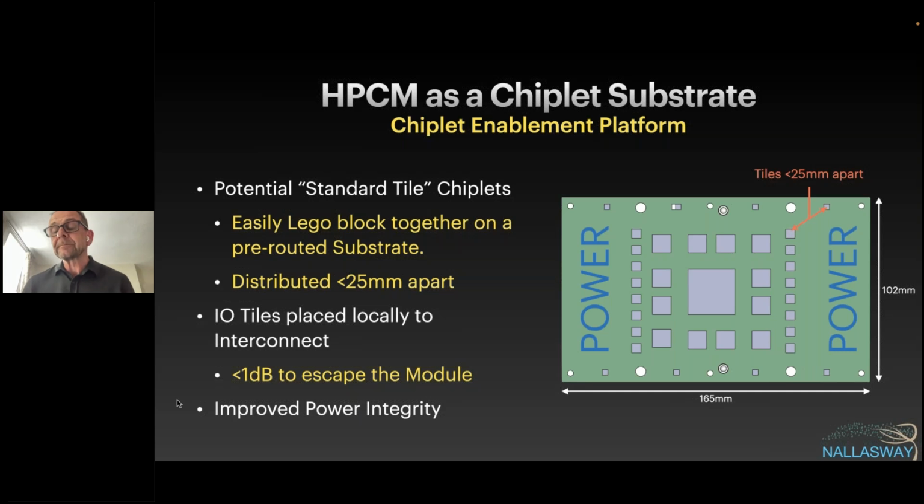Alan? Yeah. So the question is, all the connectors are on the backside of this. Correct. Have you looked at, and you mentioned something about having the IO chips over these connectors, but at least in this cartoon, you're showing one central larger chip, or it might be multiples. Yes. So connecting from that over to the IOs, have you thought about what that might look like? So I'm assuming that's a bunch of wires interface from one of these edge chiplets to the IO chiplets, right? But it needs to be less than 25 millimeters to obey the spec, right?